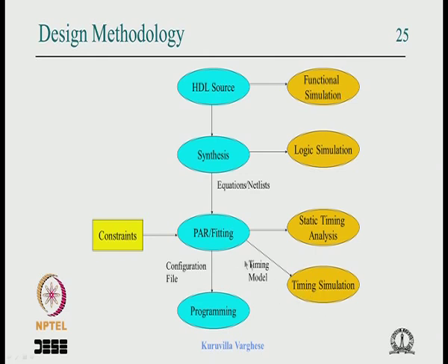So for a complex circuit it might take a day to simulate. At the beginning, when you do the first iteration of the place and route, if you go for timing simulation, take 6 hours to simulate, and find a small error, then coming back and correcting it is a very hard thing to do. So there is something called timing analysis, which is static timing analysis. This is dynamic in the sense that you give the input, you literally make the circuits work from the input to output.